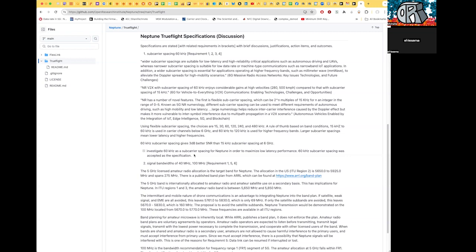Our core, next to the center frequency, all of the stuff that you absolutely have to have in order to identify the signal, to find your signal, to stay connected, needs to be fairly close to the center frequency. Maybe that's our 40 megahertz. But in the case where we have the ability, whether capacity from the channel itself or because you have a better radio chip, you just sprawl out and you're able to go to 100 megahertz. That may be what we want to do in order to allow it to be adaptive, something that your hardware can take advantage of, and it's in the protocol.